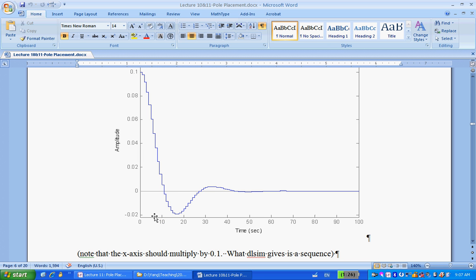As a matter of fact, you should always have certain error because the design is based on a continuous specification. After discretization, after sampling, you always have a certain degree of mismatch. So that's okay. In terms of the overshoot, that has something to do with the zeta value. The zeta is 0.46 right now. If you design a different zeta value, let's say 0.6 or 0.7, you should expect less overshoot. In a future lecture, we'll have another design.